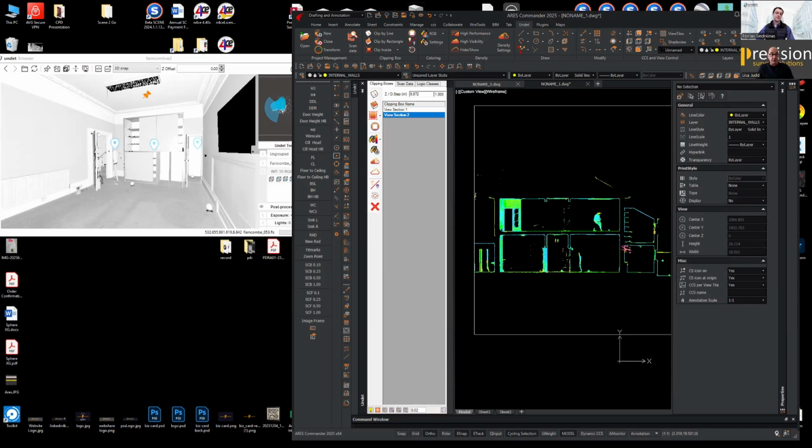So we've whistle-stopped through a lot of the tools and bits and pieces, but point cloud engines and plugins are quite difficult in some of the native solutions that they have. Again, straight out of the box, you'll be able to cut yourself a line section or a rectangle section. You'll be able to change the colors of your point cloud very easily because the tools are simple. And with the browser, you can navigate your way around super efficiently.